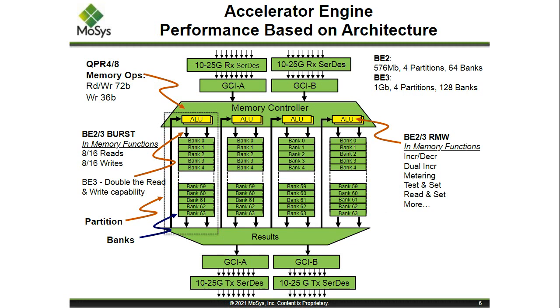But if you look at the top of the slide, the 10 to 25 gig, you see the RX SerDes lines. So MoSys has defined these parts and used a SerDes interface as opposed to a wide parallel bus. We wanted to do that for a few reasons. It does ease design of the PCB because SerDes are relatively easy to lay out, even at high frequency at 25 gig. They're not that difficult to lay out anymore. It's very common to do.